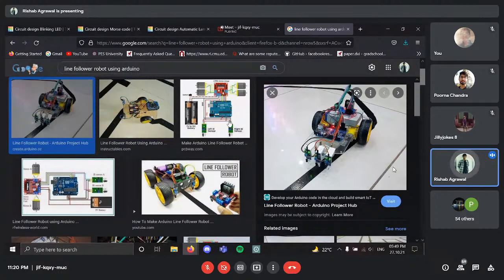The way this will be done is you basically have two LDRs. That's the reason I was pushing on LDR. The LDR will just take the input of the brightness of the surroundings, and just assume that the brightness decreases in a continuous and uniform manner as the car is deviating from the path.